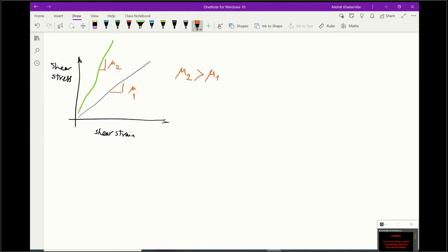Let's solve question 9. So we know the formula: tau is equal to mu du dy. We have a formula for u. Let me write the formula. Okay, so the formula for u is this: 2y divided by h minus y squared divided by h squared.